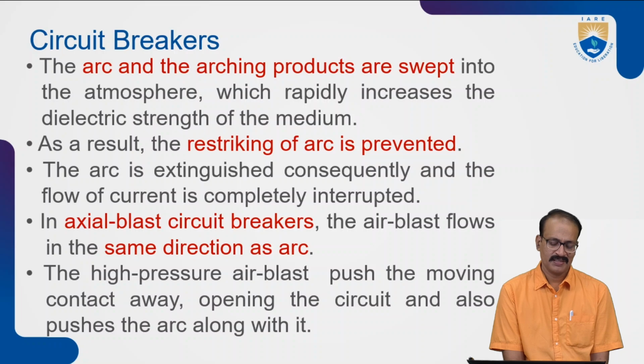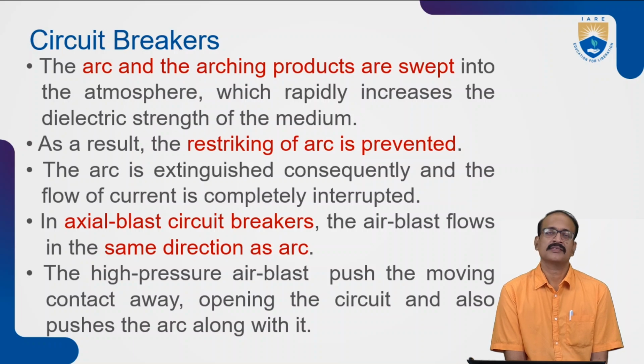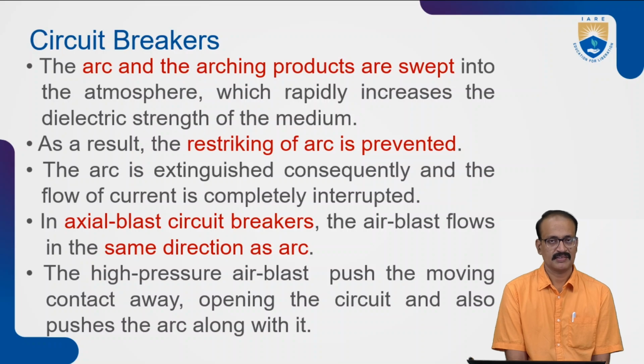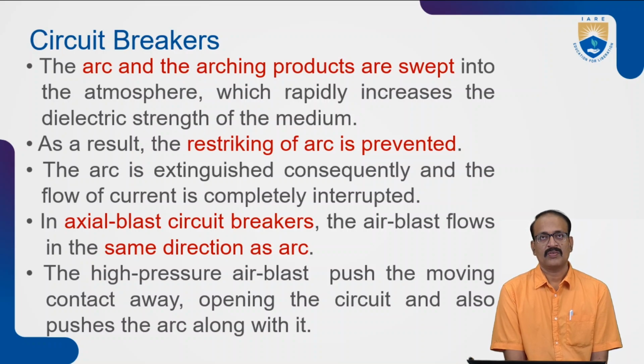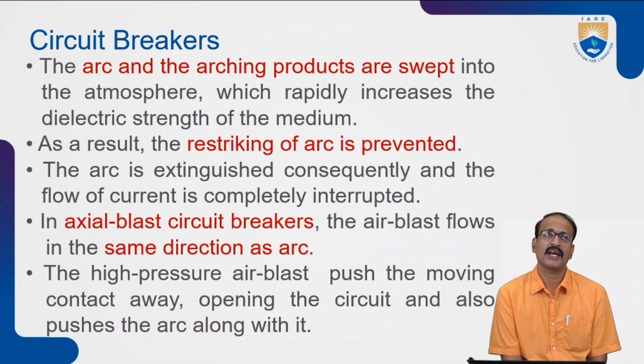Now these arcing products have gone, and there is a remarkable distance between these contacts, and there is no sufficient potential difference between these contacts. That's why the restriking is prevented. If the ionized particles were still there, they would normally decrease this dielectric strength.